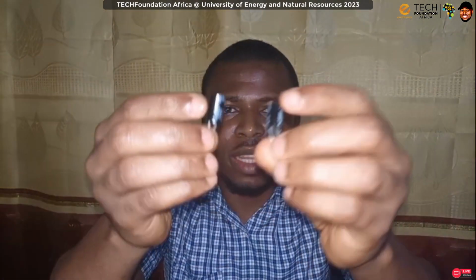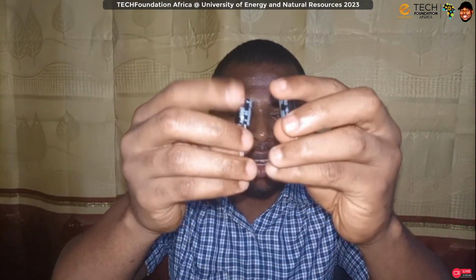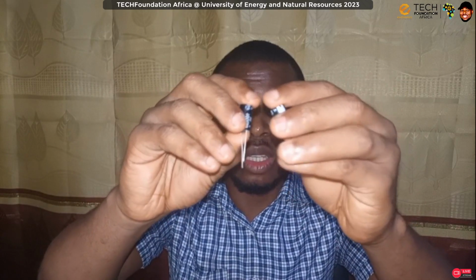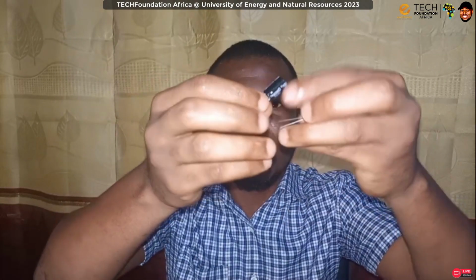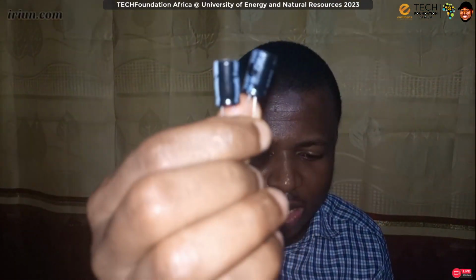Then from the switch, we have capacitors. And yesterday, I explained that these capacitors are serving as temporary energy storages. We need these things, one, to smoothen out the power coming in, and also the batteries or energy source we may be using may not have the tendency of discharging fast enough for the pace at which our circuit may desire energy. So putting a couple of these together serves as a power buffer for our circuit, so that our circuit can actually get energy as fast as possible.